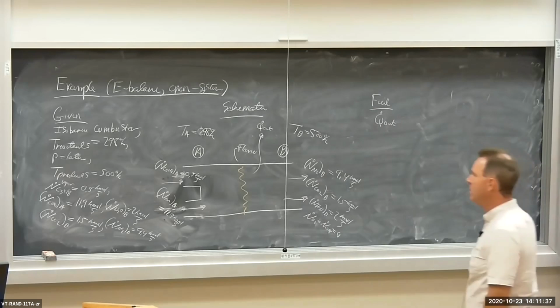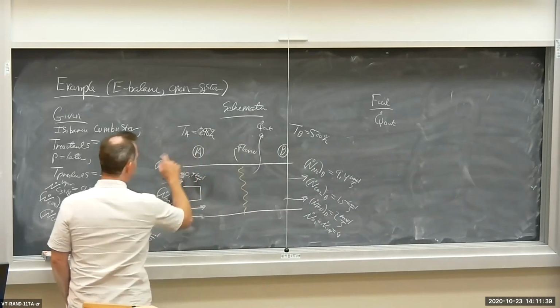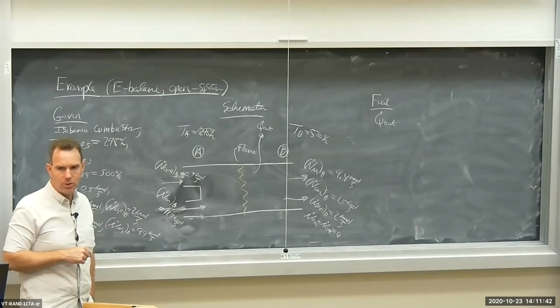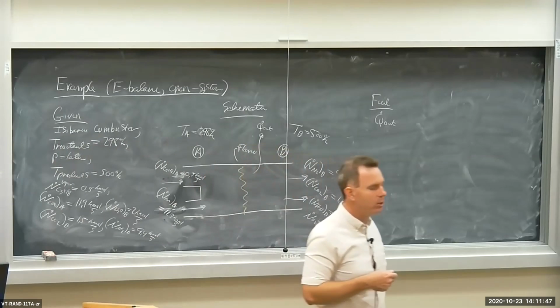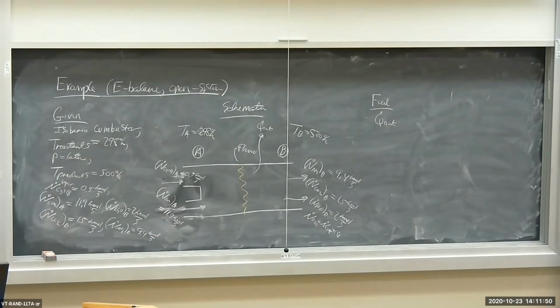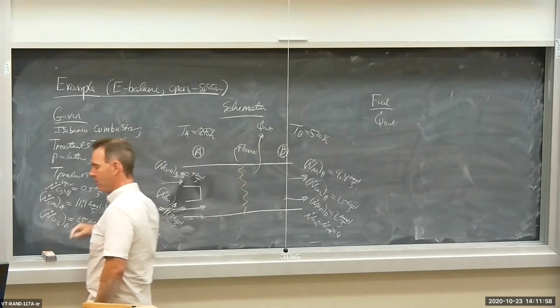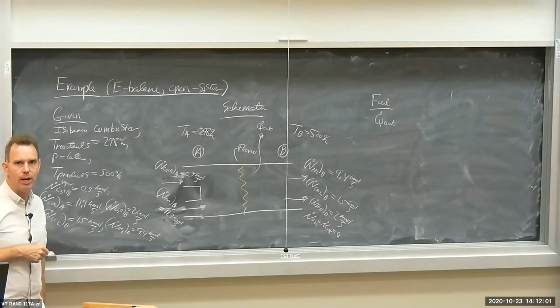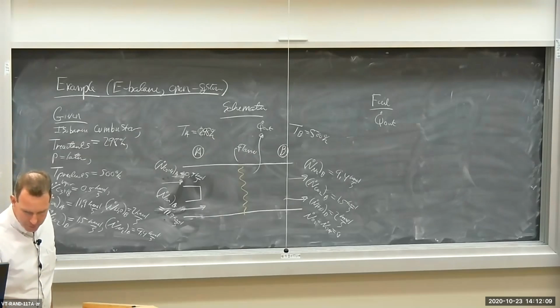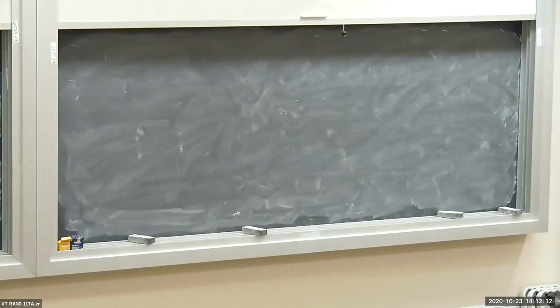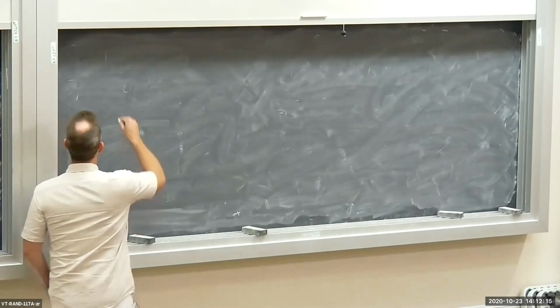I want to point out that I made the problem even easier: the reactants are at the reference temperature, 298 Kelvin. That makes the calculation of the properties a little easier, especially on the reactant side, and kind of simplifies the problem. But the intake need not be at the reference temperature; it could be any temperature. This way we don't have to calculate a delta H to get the absolute enthalpy for the reactants. All right, so let's go to the analysis here. Let's get started. So, analysis.